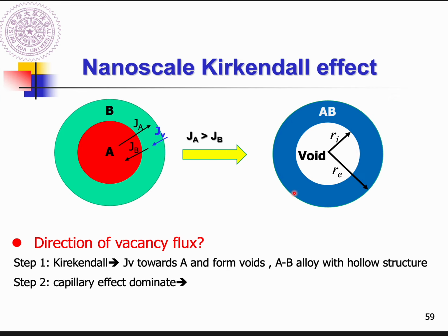So if you continue heating the materials up, the capillarity effect is going to take over and dominate the following process. The capillarity effect tells you the atoms at the convex region will move toward the concave region. So there's an atomic flux toward the center.